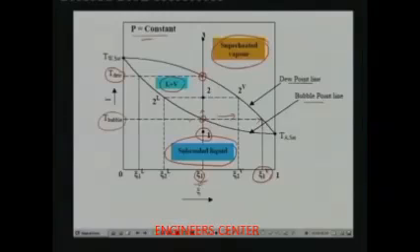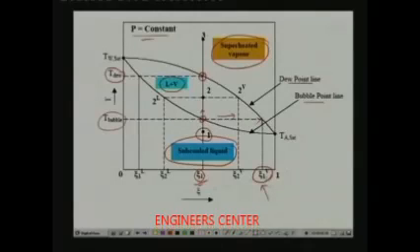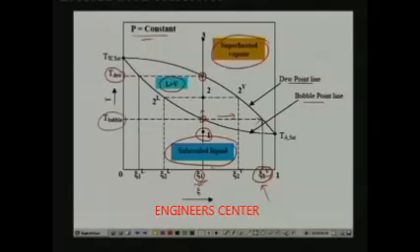The vapor bubble that forms will always be rich in the low boiling point substance. In this particular case, that happens to be the ammonia. So that is what I am showing here. The first vapor bubble is quite rich in ammonia vapor, so the concentration is given by zeta 1 V. V stands for vapor, as I explained.